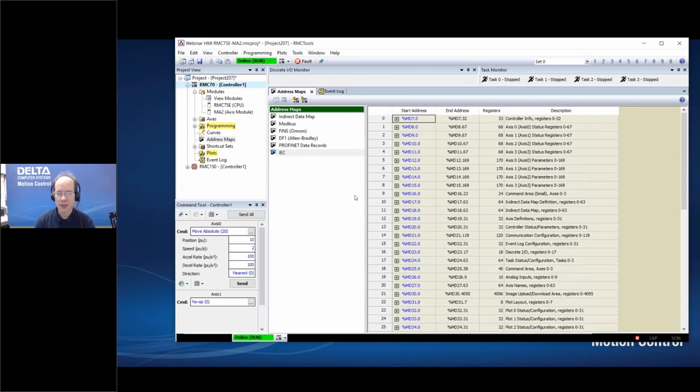You basically have to get something like a Windows CE or something that supports maybe just full-blown Windows, where you can actually program your own application in there, because it requires a lot of processing, a lot of high-speed data to actually be able to trend a plot or really upload it in anything relative to real time. So the short answer, I can't really do that.